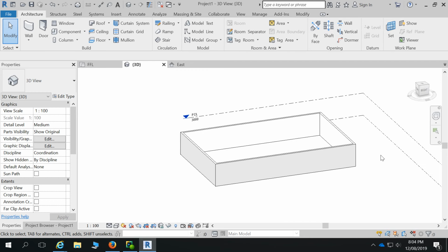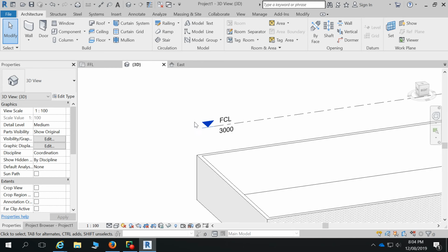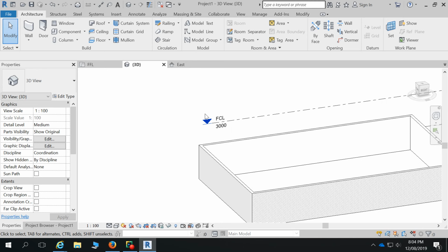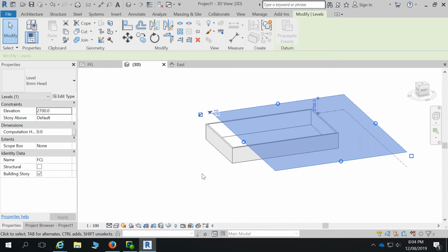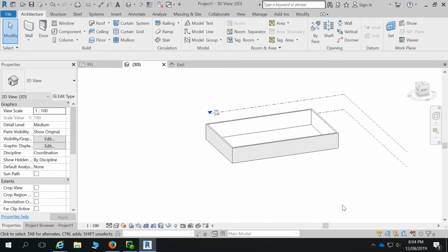So if I've decided that I want to change the height of these finish ceiling level now, the client says actually our budget's not going to stretch for 3 meter ceiling height now, it's going to probably only cover a 2.7. I could actually change that height in there to 2,700, and because I've constrained all the walls to that height, they're all going to drop down to that level.